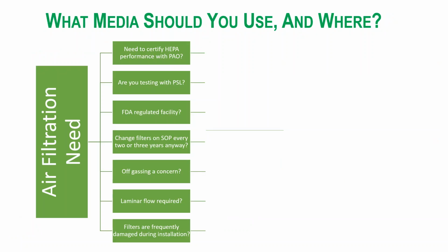So what media should we use and where? Again, there's a couple different choices now, which might be confusing for some. When do we use PTFE? When do we use EnerGuard? When do we use glass? The long and the short of it is, keep using glass. It's not necessarily a huge reason to change at this time. As the technology evolves, that might change. But right now, if glass is working for you and you're not having breakdowns or issues with testing, stay on the status quo. There's no reason to investigate that.